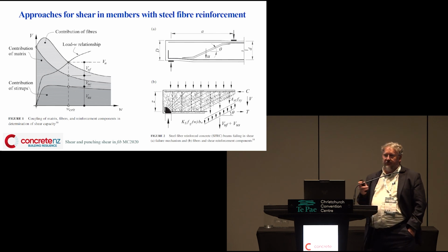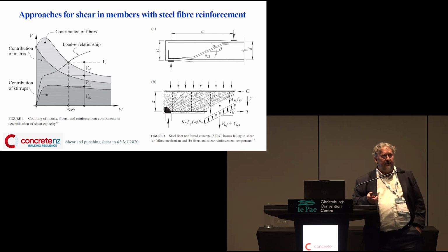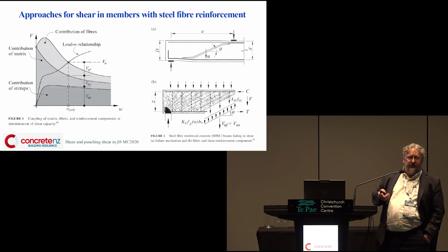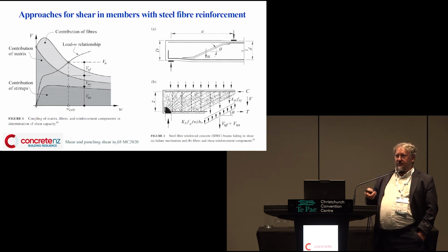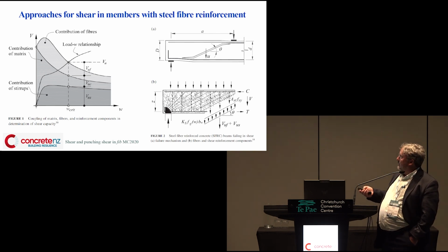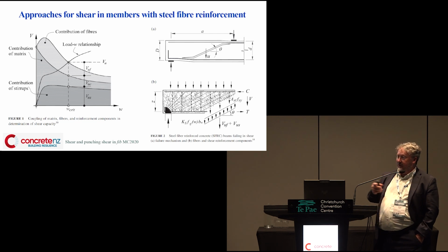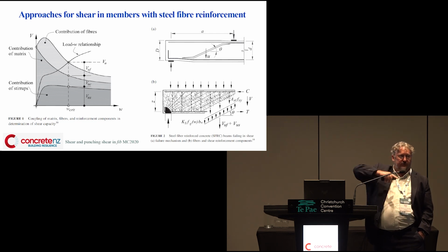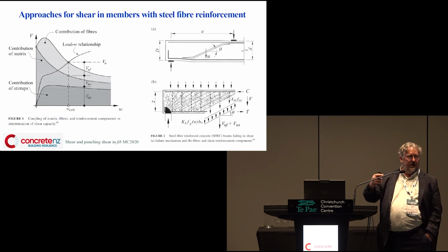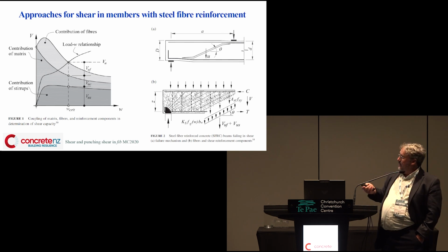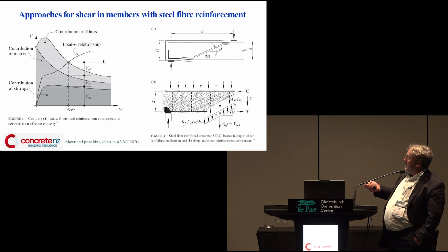So what is changing? Well, it's the strut angle, right? The strut angle is a function of the strain. And as you go up with higher crack width, you've got a higher strut angle, and the steel component actually slightly decreases. So all three are combined there, and because of crack width, we're going to get a consistent approach.